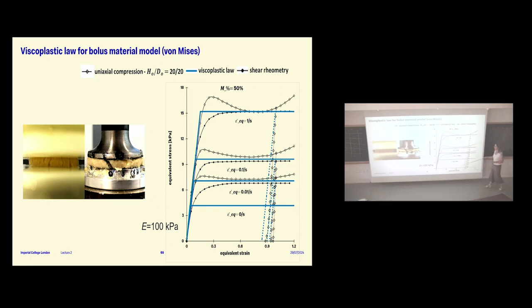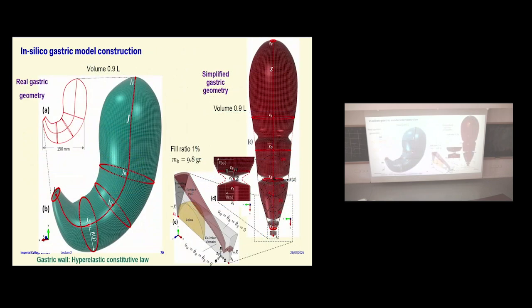And we got the stress-strain curves. These are plotted in terms of equivalent stress and equivalent strain from the two types of tests. And instead of modeling the dots as they were, we simplified it with the red lines. Okay, so it's elastic, perfectly plastic, and the plasticity is dependent on rate. Which is a simple model, and then we can put that inside your finite element software.